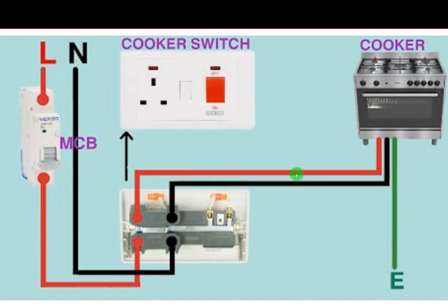But some people go and buy the plug and attach it to this and use it to plug here. And in just a few weeks or few days, here will go bad because this place is rated for 13 amps only. This socket is for 13 amps.